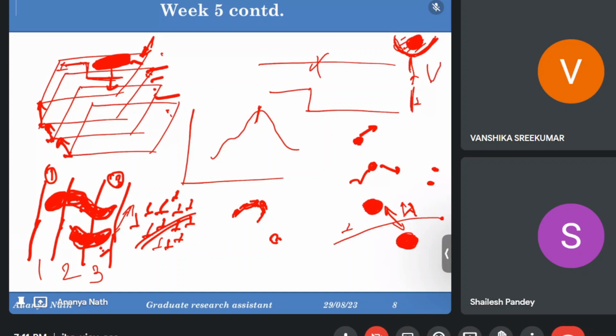If the distance between these two divided dislocations is not enough that a solute atom can come and sit over there, then it will not be a preferable site for the solute atoms. So in that case, the stacking fault energy will be higher, and nobody wants to come and sit in a higher energy state. They always try to go to a lower energy state. So this is why this stacking fault energy can be overcome for the dislocations, and they can move easily.